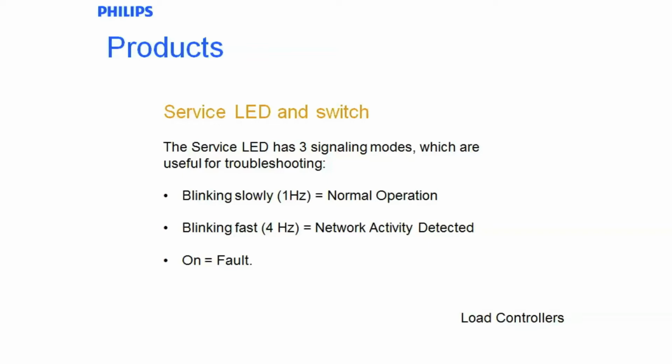If the LED is on all of the time, there is some form of fault. Likewise, if it is off, there could also be a fault. It should not just be assumed that there is no power. Always double check. The service switch has a few different operations.